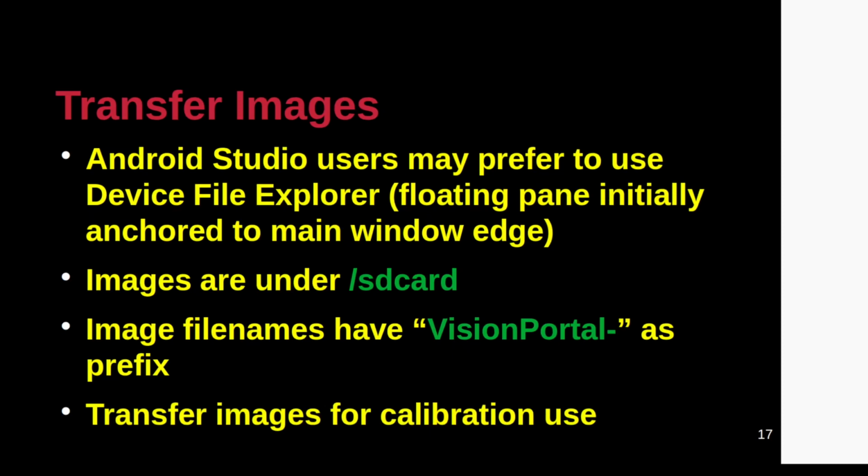Transfer the images to a folder that is accessible by 3DF Zephyr Free. If Android Studio is connected to the control hub, then its Device File Explorer window pane can be used to transfer the captured images with standard drag and drop operations, especially if you are in a Windows environment.